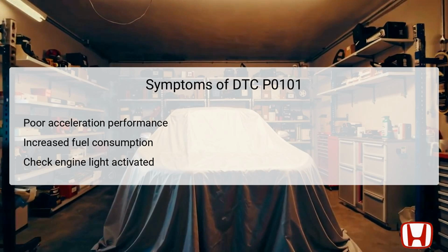Furthermore, the activation of the check engine light serves as a warning to the driver that a diagnostic trouble code needs attention. The MAF sensor directly influences engine performance, and any malfunction can also lead to rough idling or inconsistent engine behavior. Being aware of these symptoms can lead to early detection of problems related to the MAF sensor.